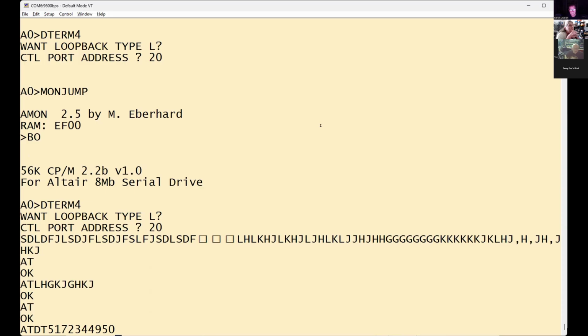Okay. Yeah, I can burn one of those and send it over. I don't really have any hobby EEPROM programmers. That's my problem. Things like those TL866 programmers or any of those other style programmers. I only have commercial programmers here. Well, that's what I was thinking, is maybe there's still something different in that file that XG Pro doesn't know how to deal with. Yeah, that could be. But if I have a good PROM, then I can read it in and I'll be able to see what's different.